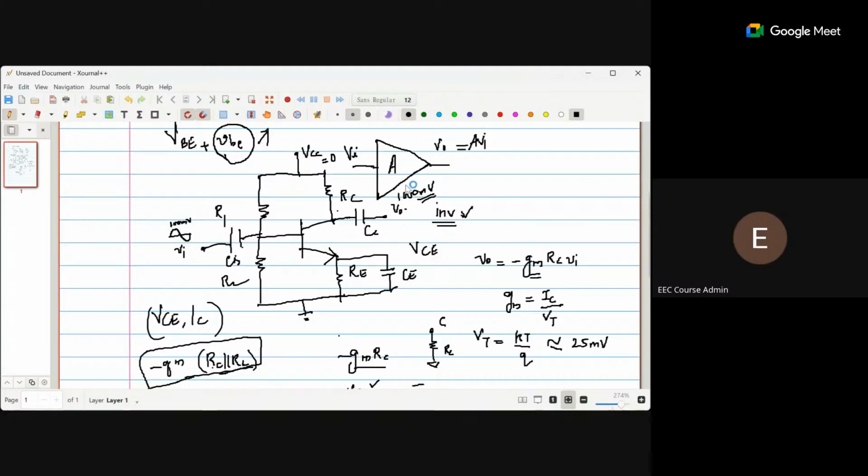That's it. Now you are going to replicate this common emitter amplifier one more time, so that you will have a matched resistors case, and we talk about the differential amplifier. In a differential amplifier, whatever is in common between the signals needs to be eliminated, and only the difference between the two input signals needs to be amplified.